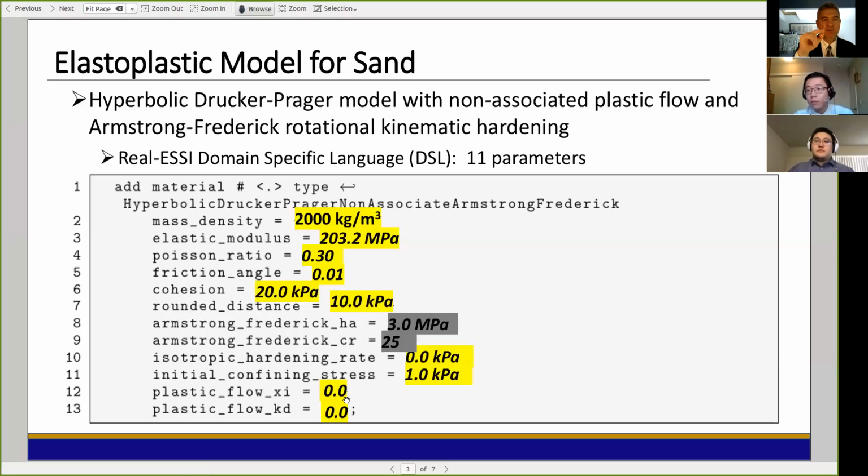Yes, Professor. These are really important if you have a coupled system where you have volume change. In our case, volume change might not be that important. It's a dry system. If it's confined deformation, the volume change will be important, but as you said, you need additional information. You need the volume change data. Thank you. So if you do not have this information, we will just put 0, which means you need to know that this is a pure deviatoric plastic deformation.